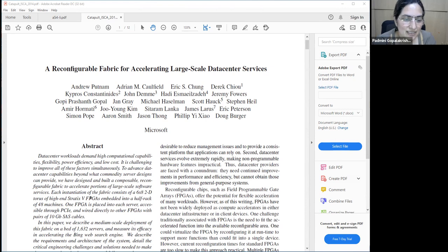Yeah, of course. It is more of an integration issue, right? If you want your application to run at a certain speed, when you design the overlay, you will have to design the system. Which means, if data is moving from the host to your kernel, which in this case is an overlay, you will have to take care of managing the buffer requirements, matching the speed of the computation. All those things, yes, definitely you will have to take care of.